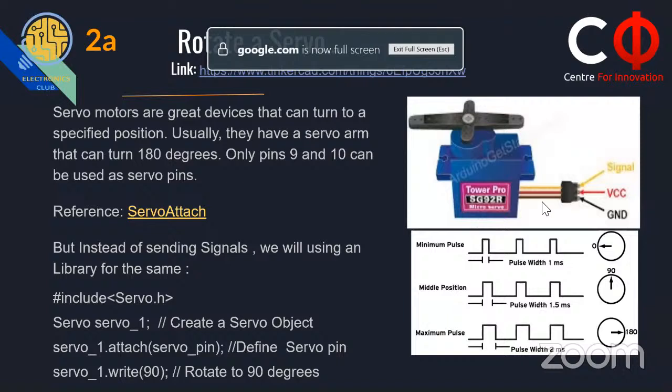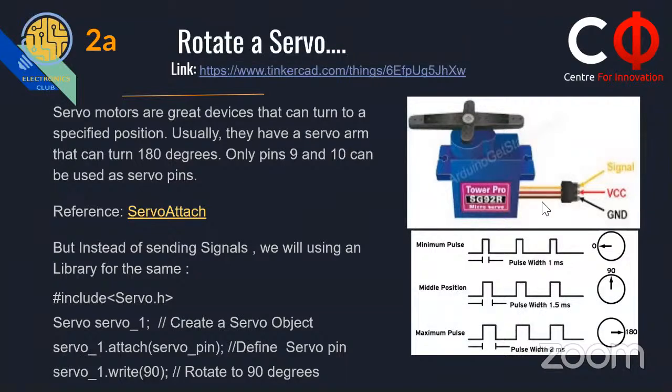All right, as we've told you, for this project we're going to be using two new components: the servo motor and the ultrasonic sensor. As we showed you how the servo motor works, using the Servo.h library and creating a servo object. Also, something that Anish mentioned is that we need to connect the signal only to a PWM pin. That is because the input to it is not just high or low. It should give a pulse, basically an analog output, that tells it to go to any angle between 0 and 180. Next slide.